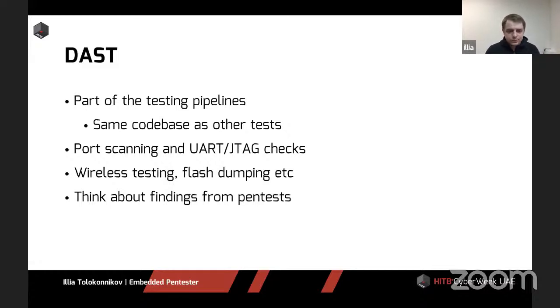And also, especially if you disable your UART and JTAG consoles in the software, but even if you don't, if you blow your eFuses physically, you also want to test that those things, especially in production firmware, are disabled, because that's the easiest way to get into your device and start poking it from a hacker's perspective.